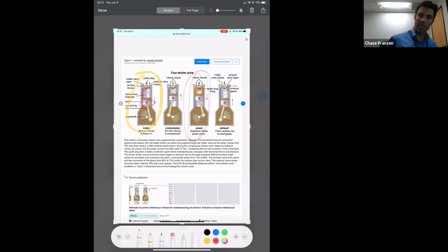We're here now in the 3rd stroke, and that shoves the piston down fast. That piston, again, that's the bang. So the piston is connected to the connecting rod, and that drives the crankshaft. So this is the power stroke. The power stroke is the one that's actually making all 4 of these pistons move via the connecting rod and is turning that crankshaft, and ultimately is giving power to the propeller.